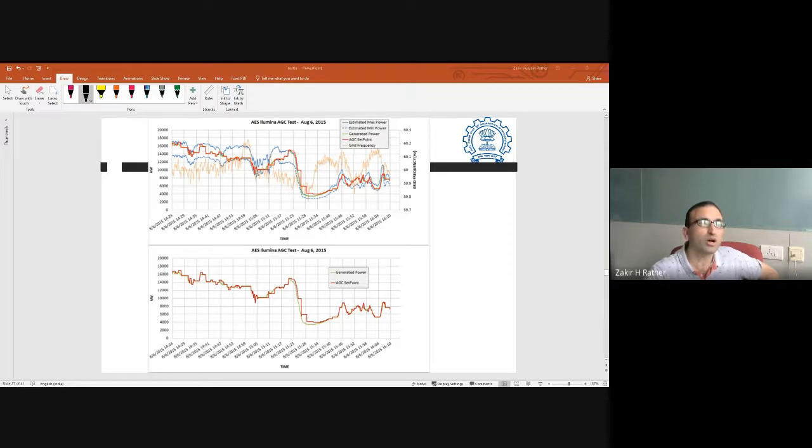So load inertia definitely is a reasonable part of this, particularly if you have rotating machines. Let us say we have air conditioning here in the country. We have industrial motors. We have other domestic motors that we use for domestic applications. It depends on the share of this motor load, which is directly connected to the grid. Again, I am not talking about drives. When it comes to drives, they will not let that happen. Direct-coupled induction motors or synchronous motors will be directly coupled anyway. So hope that answers this load side contribution question.